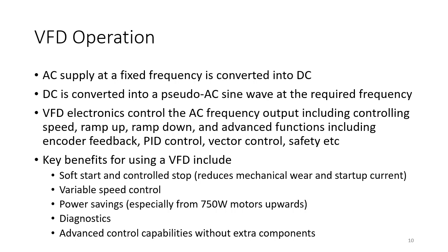VFDs can also give us diagnostics. There's lots of feedback about what the motor is doing, what the actual frequency is, what the actual voltage and current is. Particularly important for energy saving is kilowatts and kilowatt hours. And of course, we can look at things like power factor as well. And then there may be other feedback depending on what the VFD gives us. And then there are all these advanced control capabilities without extra components. So for example, a PID controller inside the VFD could eliminate the requirement for a separate PLC and reduce the amount of hardware you need to do closed loop control.